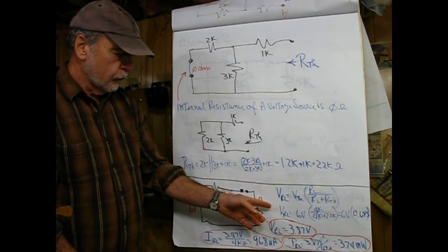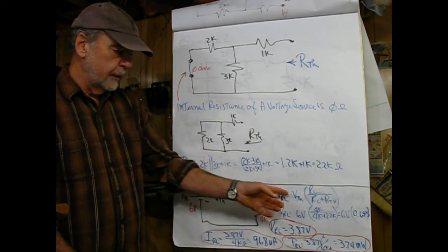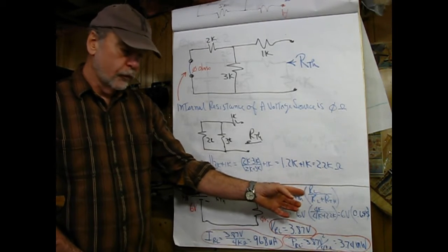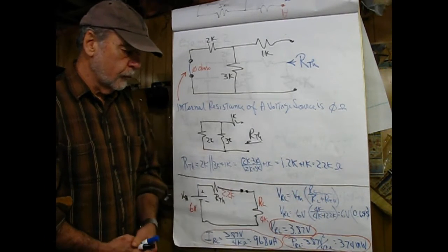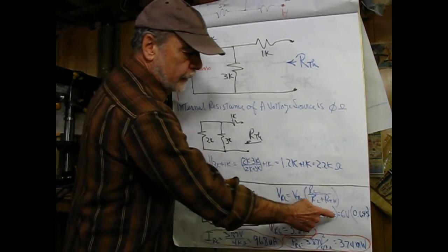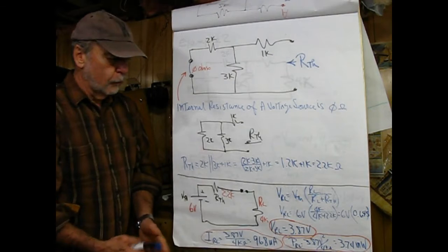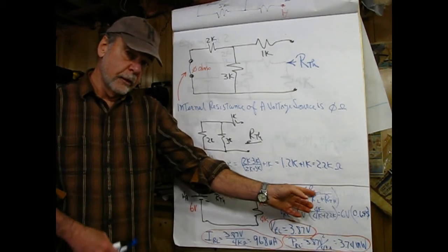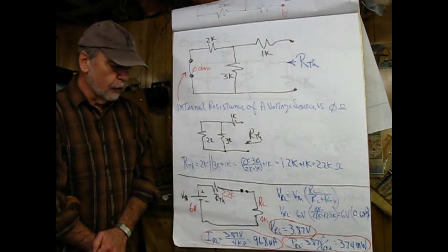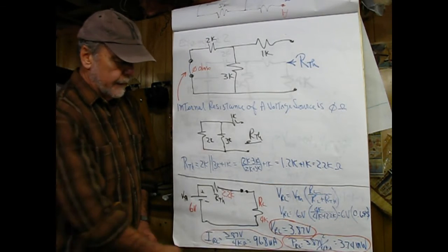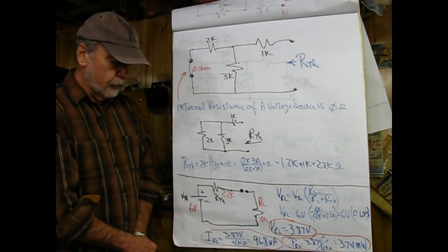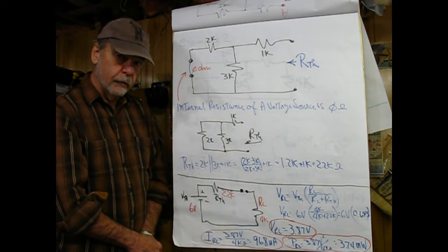So the voltage across the load resistor, the 4K, would be equal to VTH times the load resistor divided by the total resistance. No surprises there. Here you can see that expanded, we end up with 6 volts, and then the ratio of what is in the parentheses is 0.645, and then working that out, we end up with the voltage across our 4K resistor of 3.87 volts.